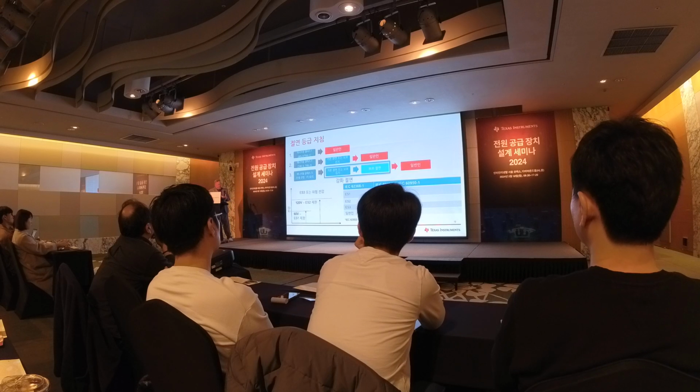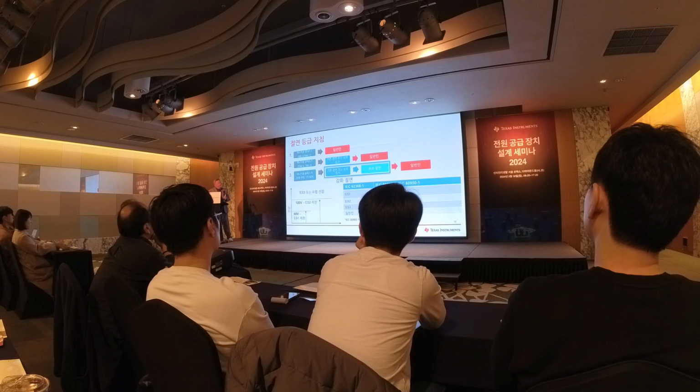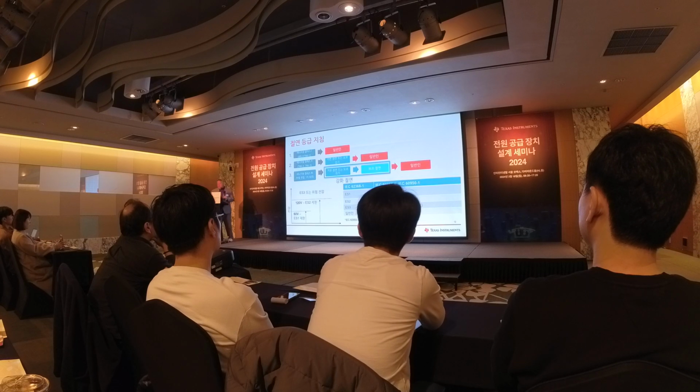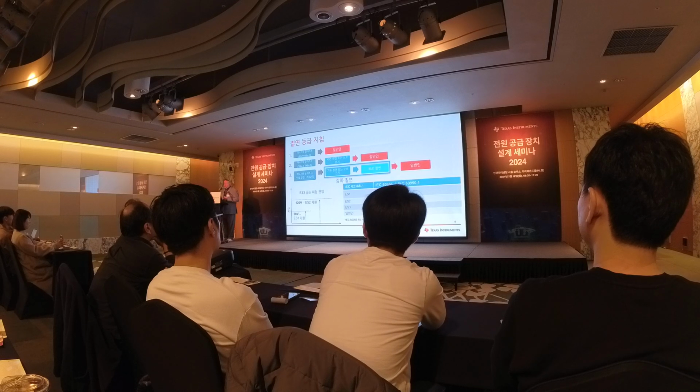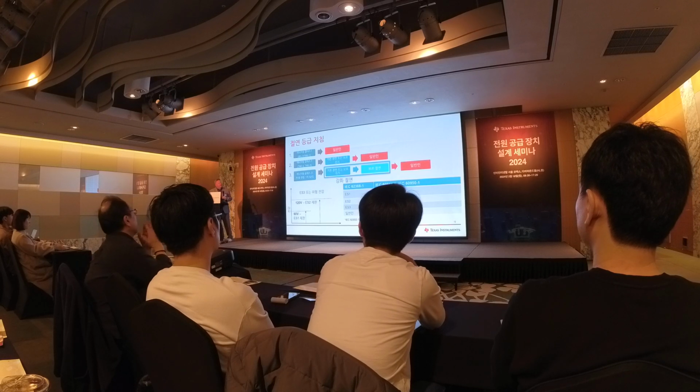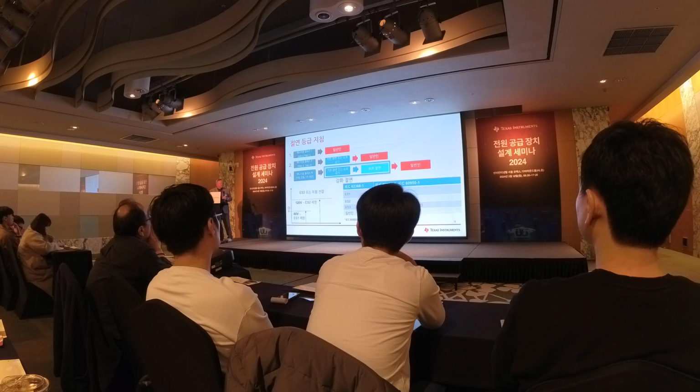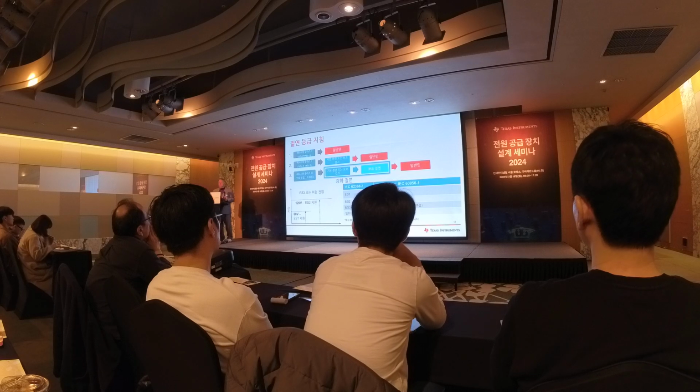Within energy source class 1, these are basically the lowest voltage. We call them SELV, or safety extra low voltage. It's basically 60 volts RMS or below. These are deemed to be safe to touch without electrical shock occurring.